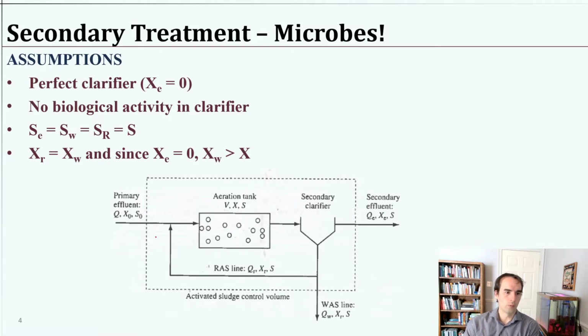Okay, and the fact that there's no biological activity in here means that we can use the volume of our aeration tank as the primary important component. And again, it's actually a decent assumption because we're not supplying the clarifier with extra oxygen. Water is just going to pass through that rather quickly, at least not for long periods of time. And we definitely don't want to be bubbling air into it because we're trying to clarify the stuff.